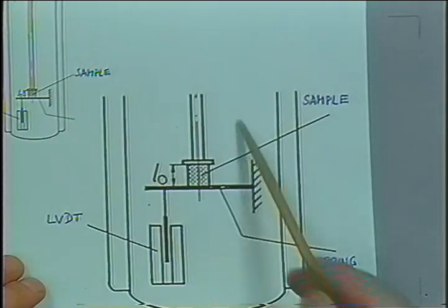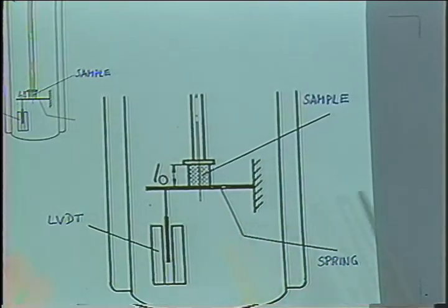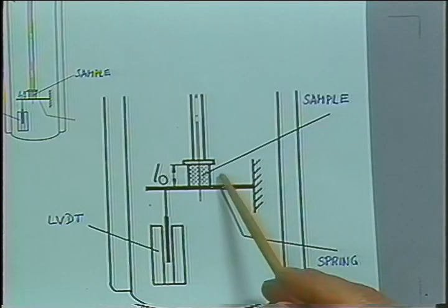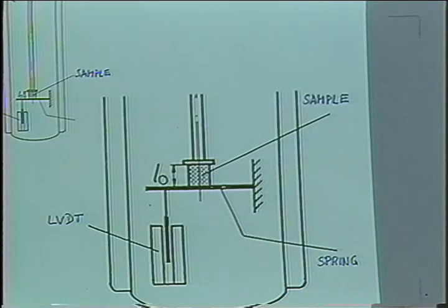All of this is submerged in a heating bath because you would like to measure at high temperatures, like polyethylene at 180 or 200 degrees C, like in a real film blowing experiment, for instance. So you want to have the real operating conditions. So you use hot oil, and that sometimes causes a problem because the oil might go into the sample, and you would be swelling your sample and changing the properties of the material. So you have to be careful about this.